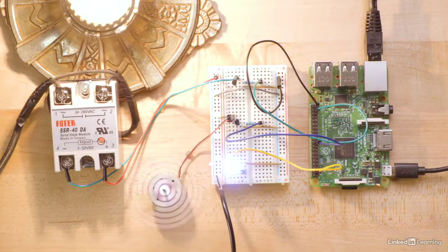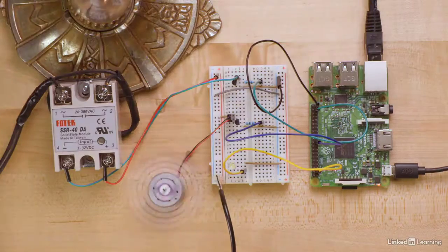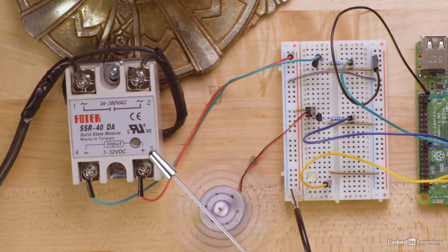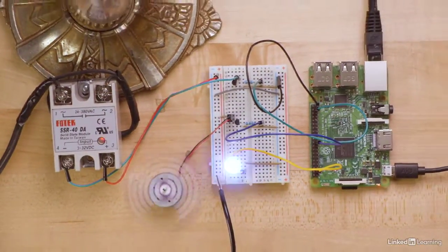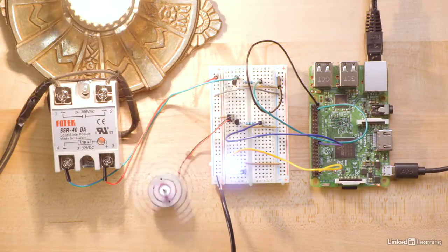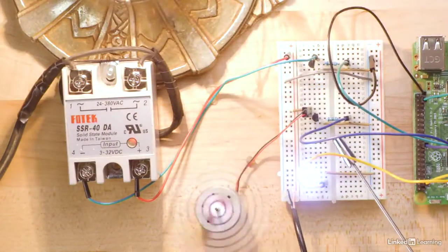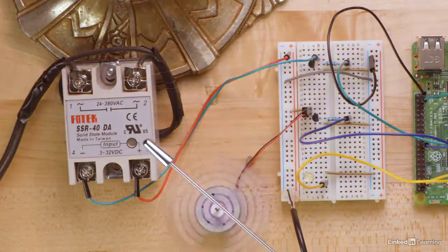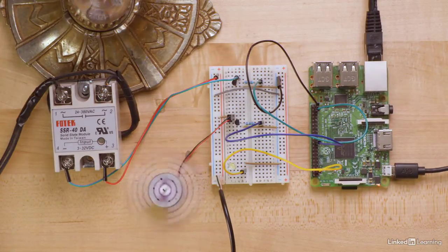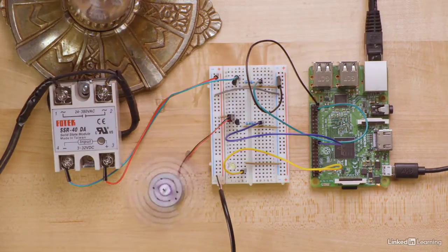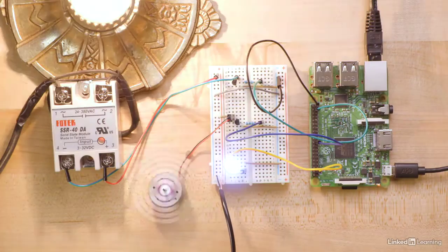The one I purchased indicated it would switch on at 3.3 volts DC, and I assumed I could just connect it to the Raspberry Pi GPIO. The signal light on the SSR, solid-state relay, would light up, but there wasn't enough current to actually activate the device. So to supply more current, I took the same transistor circuit I used for the motor and connected it to the SSR. Now I have enough current to drive the solid-state relay and control a lot of voltage. So in short, transistors are cheap and easy ways to protect your Raspberry Pi from large voltages while controlling those voltages.